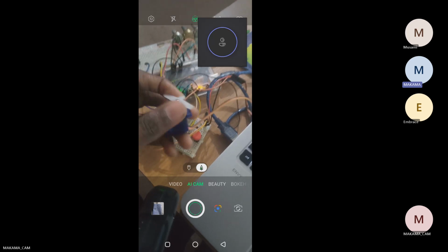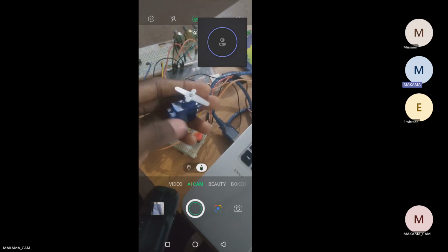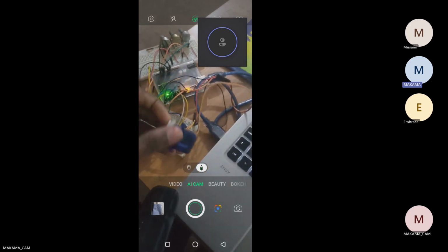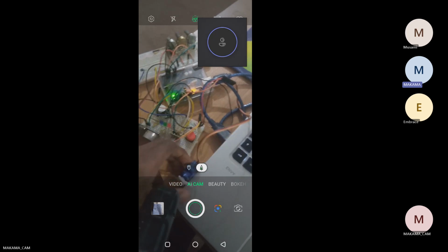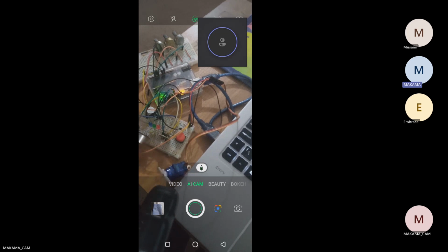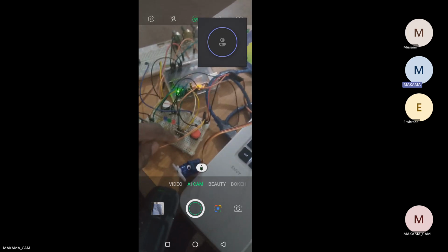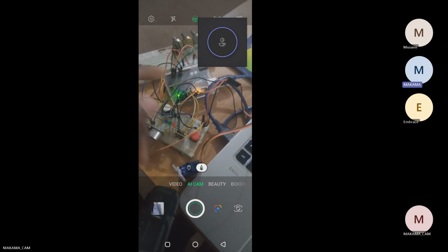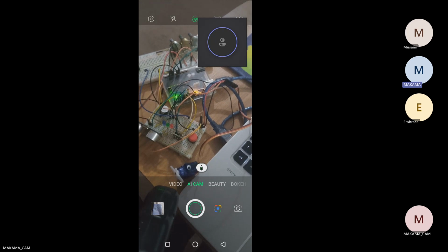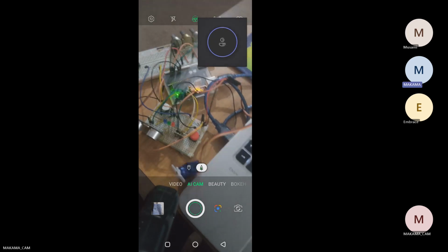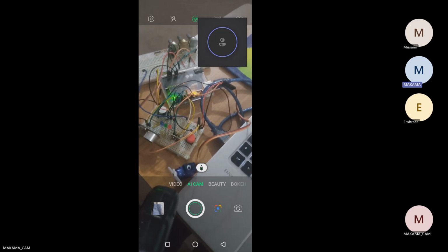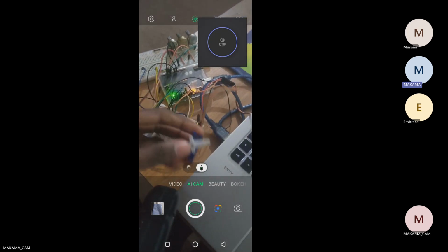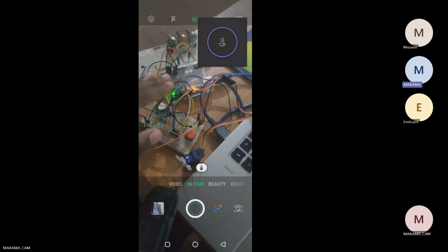You know, motors consume higher power than all these LEDs and stuff. Once you want to use 2 to 3 servo motors, they are going to drain the supply. I showed you earlier that when I powered this servo motor and one LED was on, that LED was dim. It's just like your house: once you turn on your generator and someone turns on an iron, if it is not a high-watt generator, you will see the voltage or wattage reduce. The same thing with this. Once you turn on your servo motor, another LED will be kind of dim.